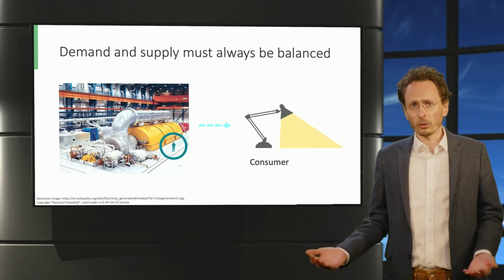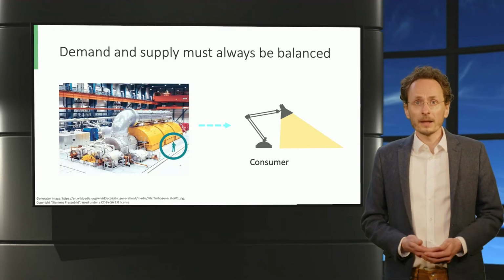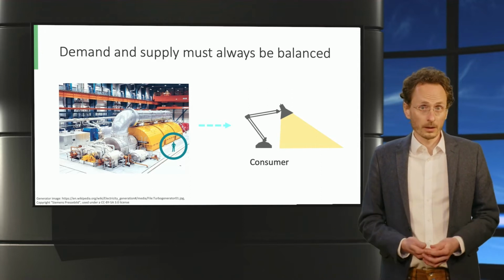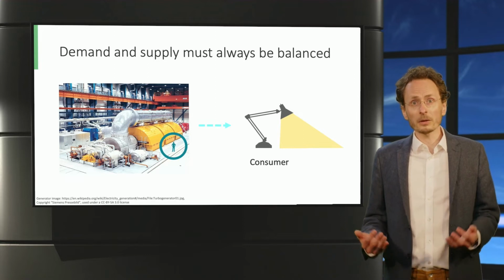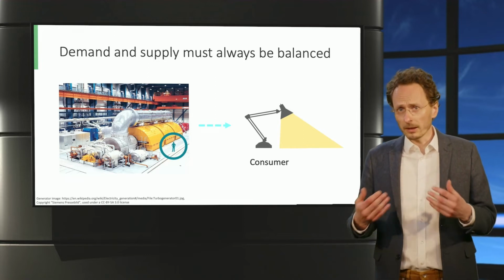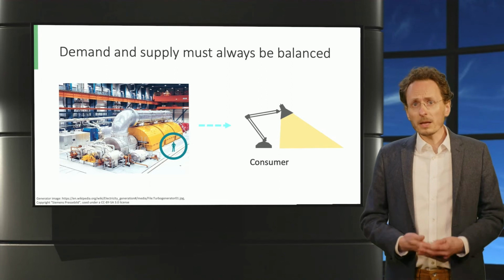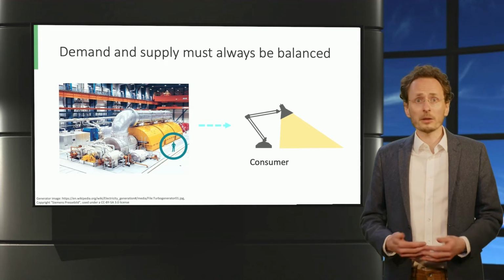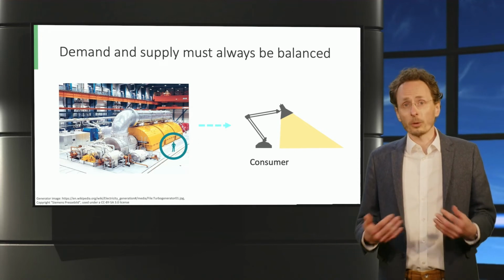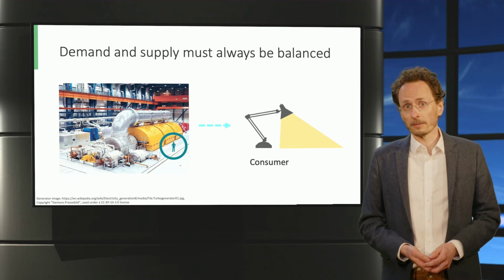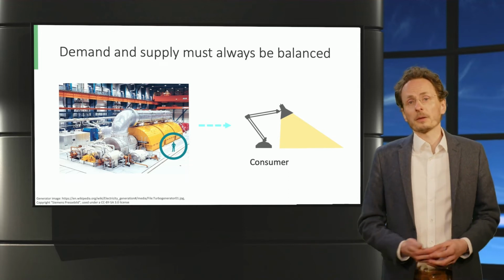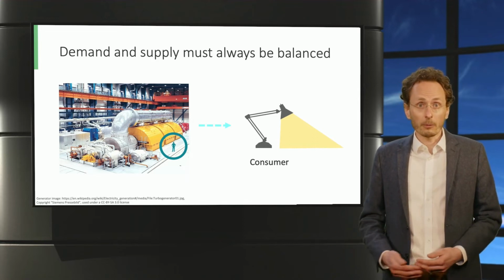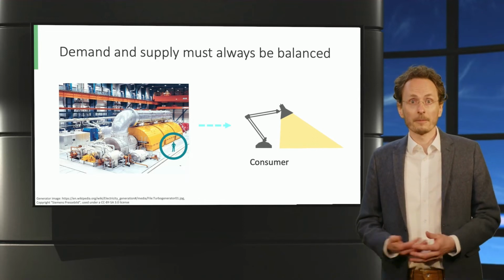If the power plant is an old school one, like a coal-fired plant, its generator is rotating 50 times a second, so 50 Hertz. When I turn on the lamp, the generator slows down a tiny bit because it must work a tiny bit harder. Immediately, the automated plant controls increase the amount of fuel being burnt so that the generator speeds up again and keeps rotating as close as possible to 50 Hertz. There are many such systems throughout the electricity grid to ensure that when demand goes up, so does supply. And when demand goes down, so does supply.